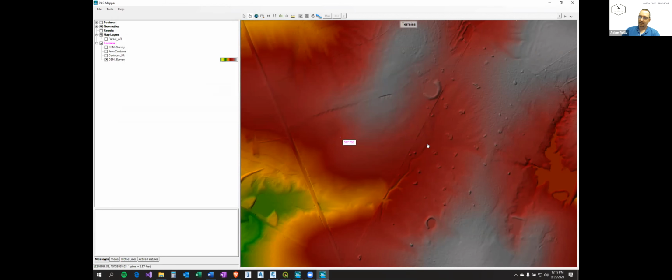With this process, you don't have to do a lot of the converting that we would do on the Civil 3D side. The contours you get from TNRIS were not properly assigned their coordinate systems, so sometimes they'll come in way off, or they'll come in meters instead of feet. All the elevation data in the shape files is assigned to meters, and Civil 3D doesn't handle that as well as this does.